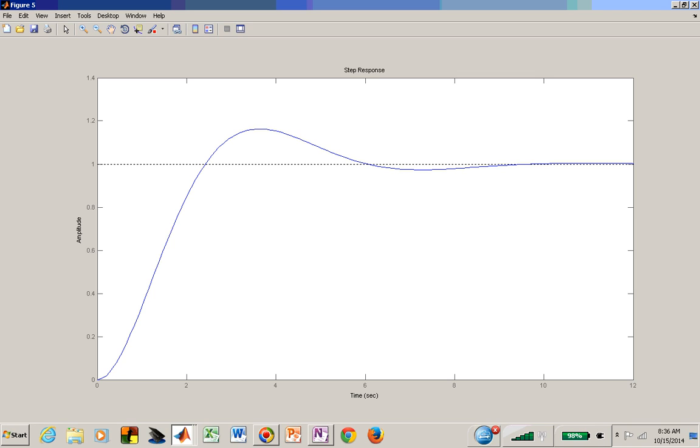You want to have this stuff available to you rather quickly. So now we have an overshoot. Those type 0 systems, which were first order systems, didn't have any overshoot. Now we have a little bit of transient behavior that maybe we're okay with, maybe not. It's slower, but what's our steady state accuracy? It's much better, isn't it? It's 0. So now if we had to compare these systems' behavior, this one, B, would be the best steady state accuracy, and which one is the worst?